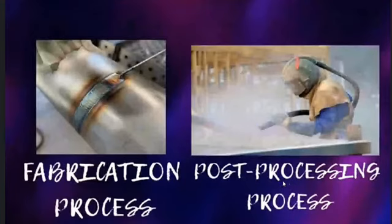So now let's discuss the fabrication process. Once the sheet metal model is formed, the corners or open gaps are welded to maintain the strength and geometry of the component. Welding methods that are generally used are TIG, MIG, spot welding, etc. For aluminum and brass parts, brazing is used for joining. Besides welding, riveting can also be considered for joining.